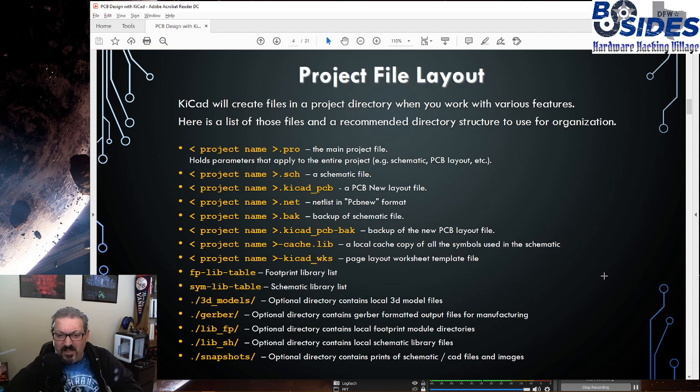And the reason for that is there's different versions of KiCad, and they're constantly making updates and changes to the library files, adding things, removing things as they move from one version to the next. And if I want my project sitting in GitHub to remain viable after new updates have come out, it has to be able to reference the same exact footprint and schematic files that I've used. So by copying them to a local library, I'm not dependent upon the global libraries to make sure that everything will work a year or 2 years down the road with this project.